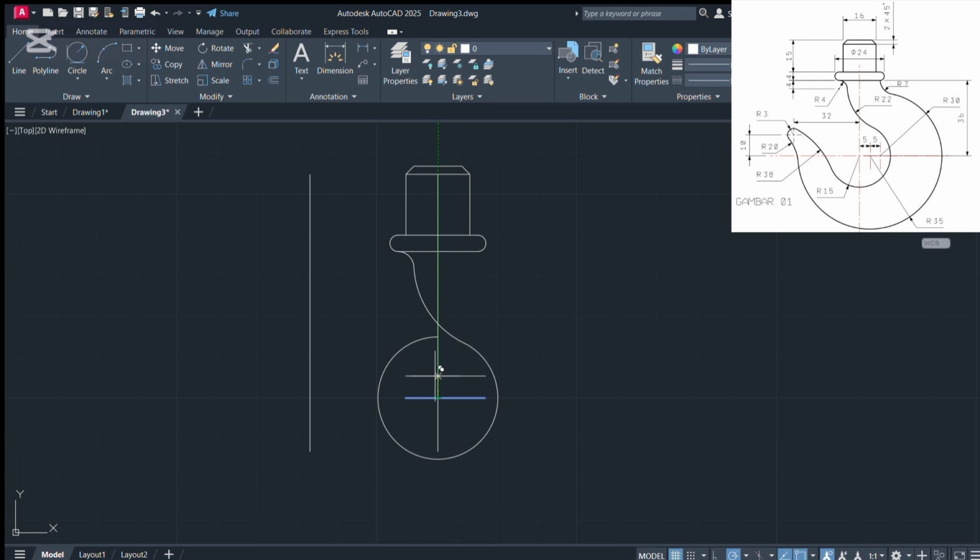From there, we have the distance above the bottom line of the center of the circle that was 15 in radius. You're going to copy that line, then drag it up at a distance of 10 centimeters. Then, after dragging it up at a distance of 10 centimeters, you're going to move the line to the new line that we had earlier done, the center line, just like this.